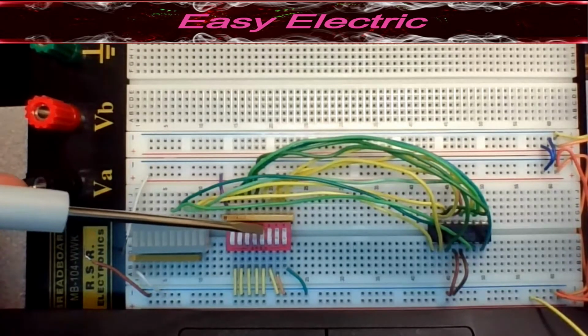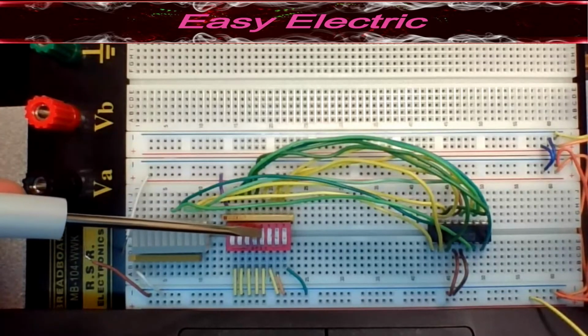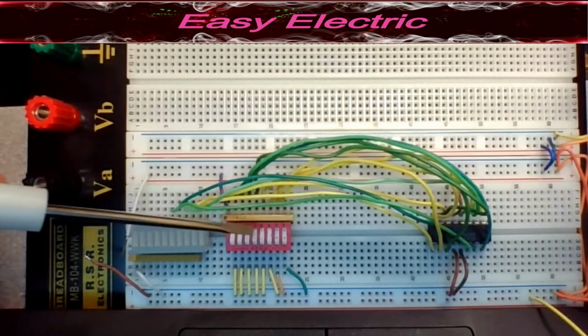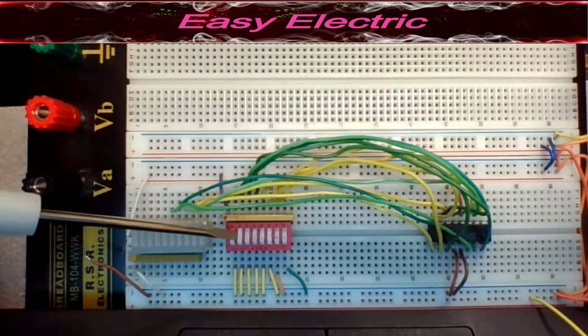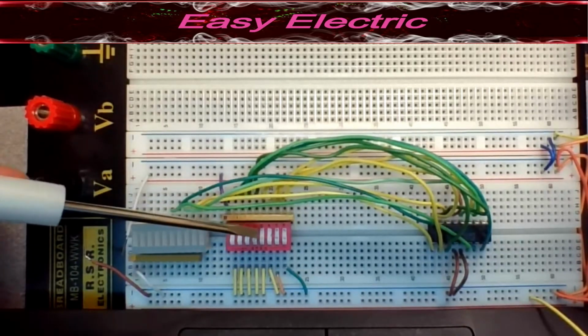Similar thing for A. This one is A4, and this one is A1. So with 4 switches you are able to give A, and with the other 4 switches you are able to give B. Because we have a limitation in the switches, we couldn't put C0 on another switch. For that reason, we just connect C0 to the ground. If you have more switches, you could add one more switch and give 0 or 1 to C0. Here, we just connect C0 to the ground. This 4 is A and this 4 is B.